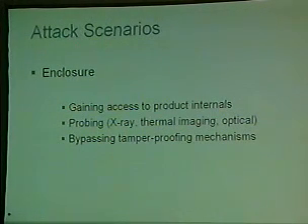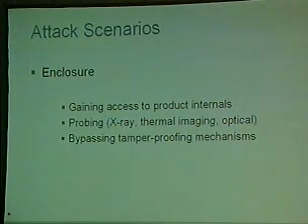Okay, so if you don't get anywhere and you're determined to get the secrets in the box, you probably go out and either purchase one or try to get one under evaluation and get the screwdriver out. If there are tamper bits on it, you have to get the proper bit and start popping it open. Also, if it has heavy tamper-proofing mechanisms, you may have to use less invasive attacks such as thermal probing or thermal imaging and X-ray. And if there are vents in it, you could also snake in a fiber optic camera, possibly to find microswitches and other types of devices to properly lock down, so when you pop the case off, it doesn't zeroize itself.